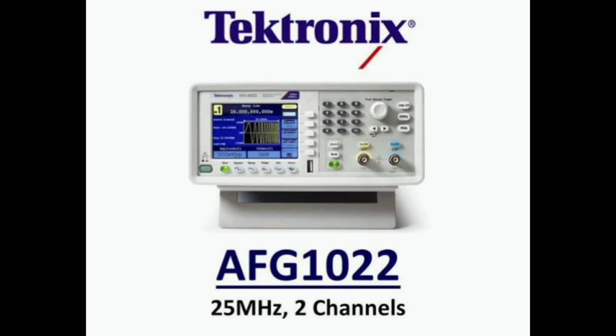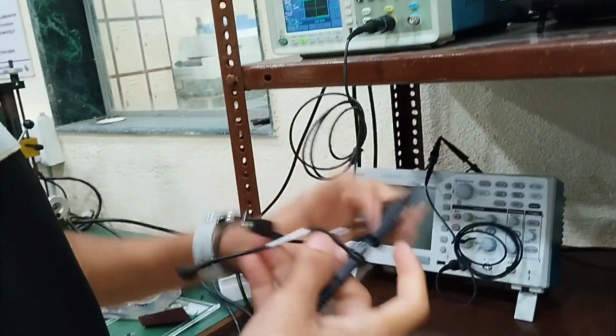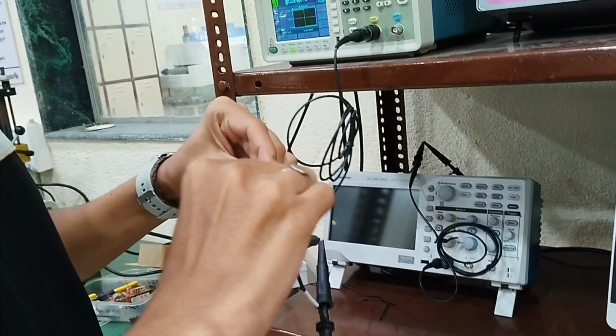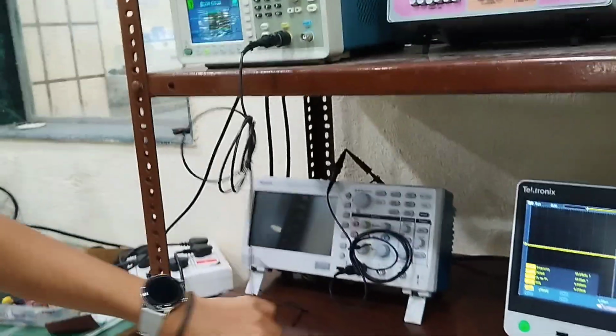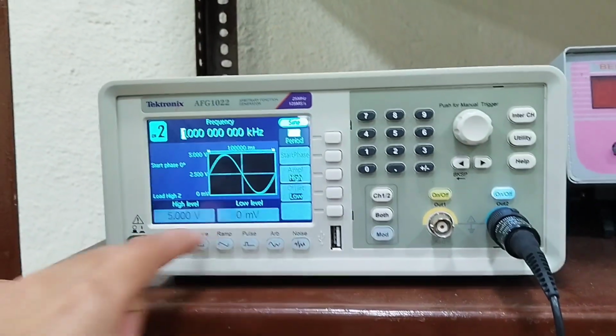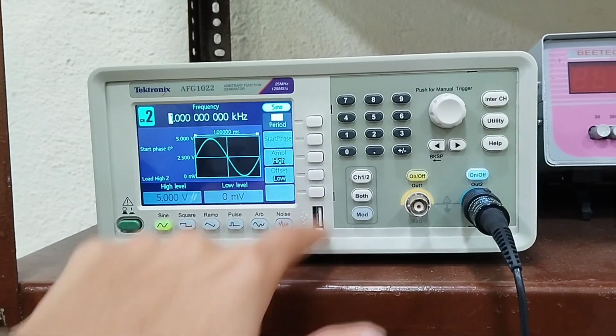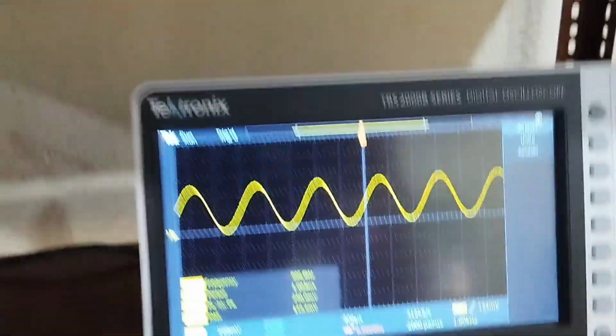As you can see, the manufacturer of this arbitrary function generator is Tektronix, and the model number is AFG1062. For the practical demonstration, I will connect the arbitrary function generator to a 4-channel digital oscilloscope. So as you can see the generated waveform in real time. This visual representation will help you better understand the front panel, which is equipped with various controls and settings. We have frequency adjustment, amplitude controls, waveform selections, and more. Understanding these features is crucial for tailoring the output to our specific needs.